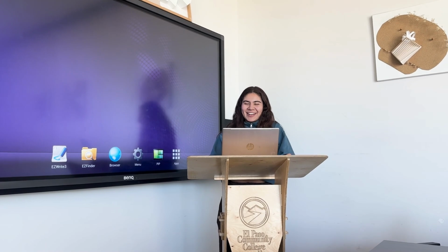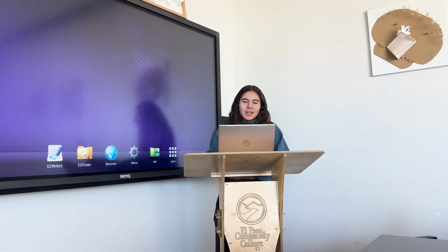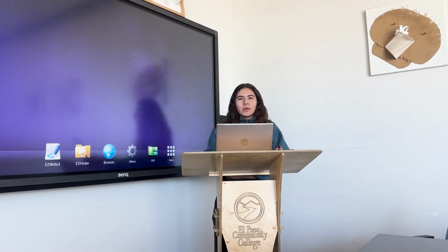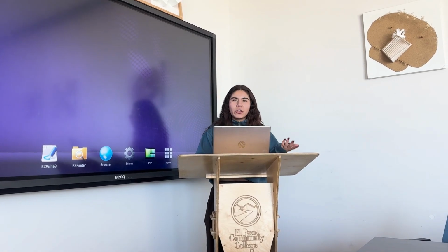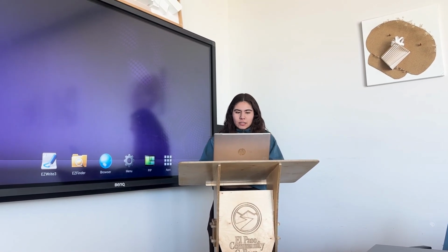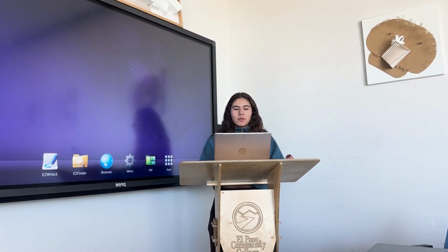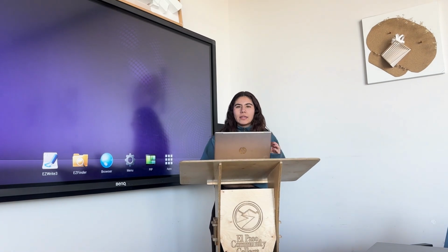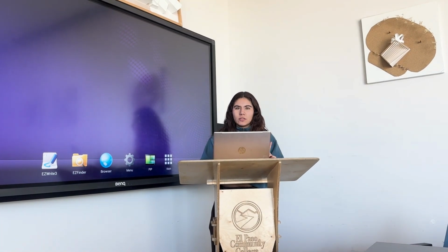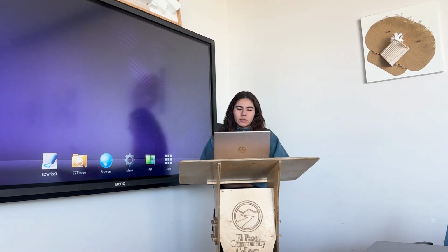Hello guys, today I'm going to be talking about detailing masonry walls. So one aspect that we have to look at when we're learning about masonry walls is the cavity drainage and the flashings. So the traditional recommended separation between widths of a cavity wall is no less than 2 inches. For those who know the metric system, it's 50 millimeters.